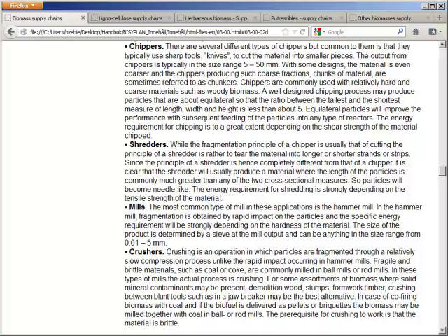And then there is also an ongoing development of new technologies whereby the fragmenting would mainly be done by slow shearing. This seems to be an operation which might produce more isometric, less needle-like particles with less of a ragged surface than the 4 types of fragmenters we have just discussed.